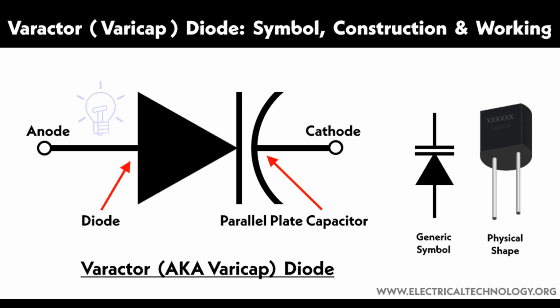It indicates how much the frequency changes for a given change in voltage. 4. Modulation. VCOs are commonly used for frequency modulation, FM, applications. By applying an input modulation signal, such as an audio signal, the VCO's output frequency is modulated, resulting in a frequency-modulated signal. 5. Applications of VCOs.